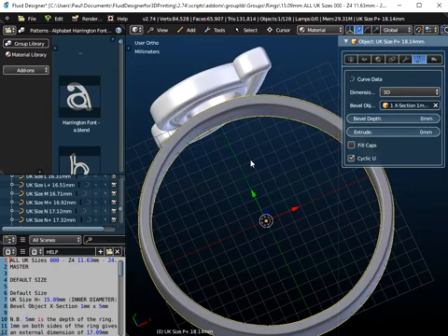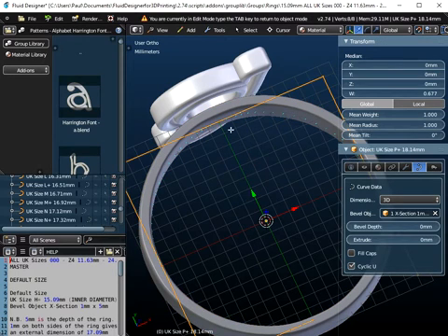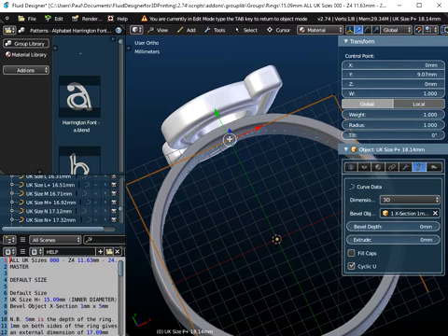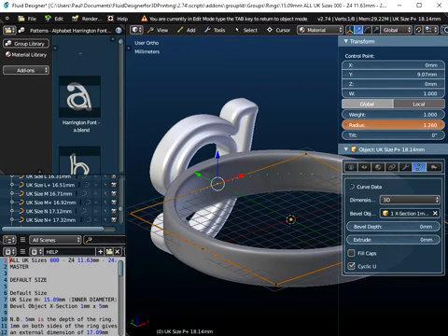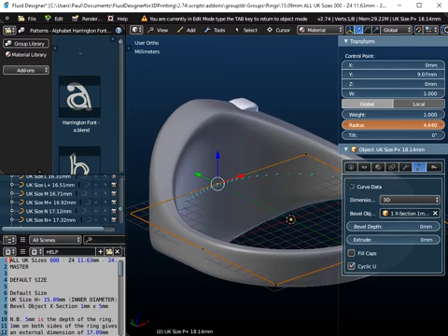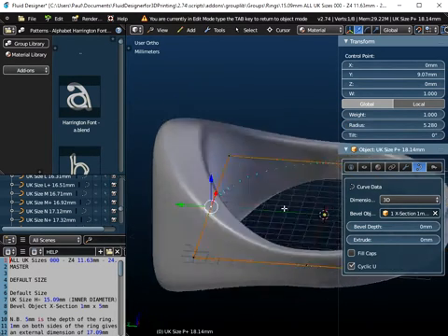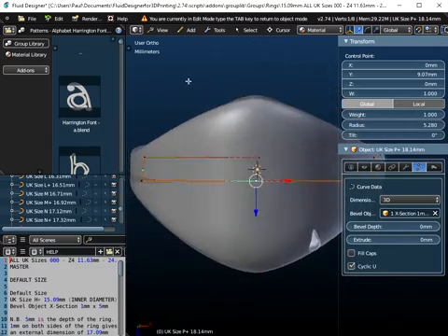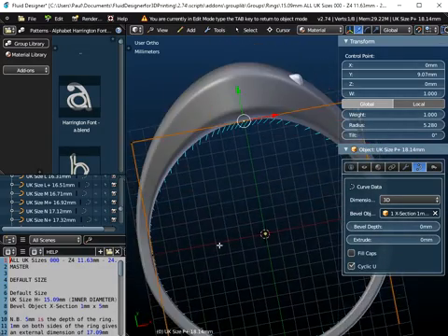So if I select the ring itself, and press the tab key on the keyboard to go into edit mode, you'll see that there are a number of control points around the object, because this is a curve. And if I select just the control point at the top there, and change this value over here, the radius, you can see what's happening as I increase this. The shape just at the top of the ring, not the rest of the ring, is changing. Now if I hold down the left mouse button and drag it, I can drag it out until it just fits outside of the letter A. Now I know the A's disappeared at the moment, but we just need to move it. So I can reshape the top of the ring, reprofile it, so that the letter A fits nicely.